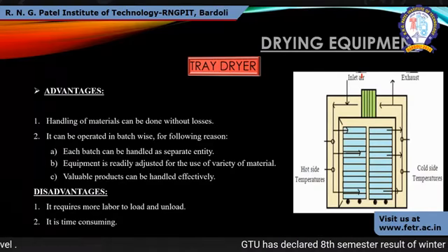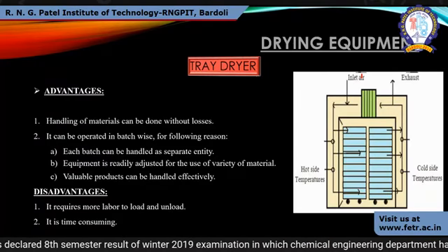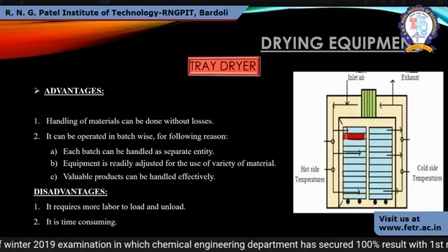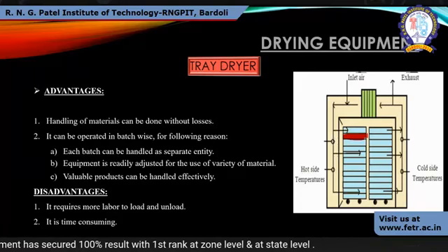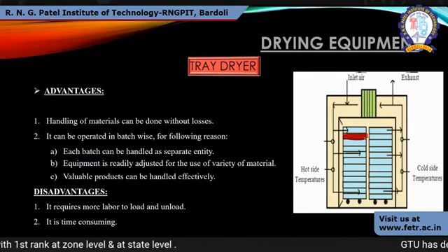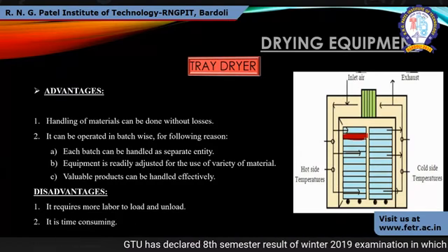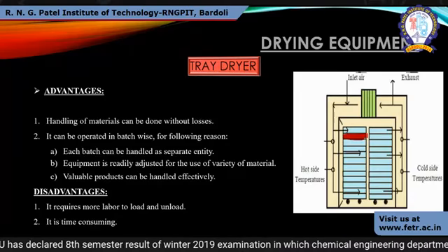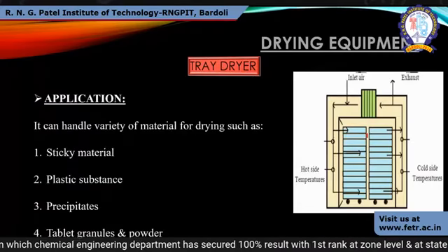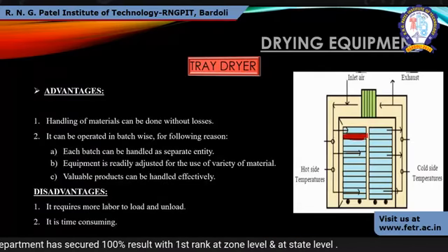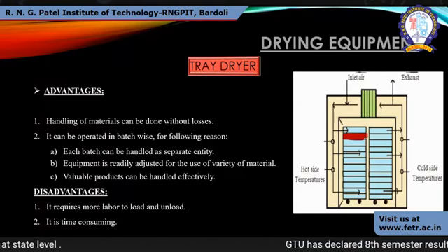The only disadvantage is that it requires more labor. We need to feed the trays, then take out the solids, so loading and unloading both need to be done by labor. So high labor work is required. And second, it is a very time consuming process, right? It is a very lengthy process for a simple batch process. Okay.